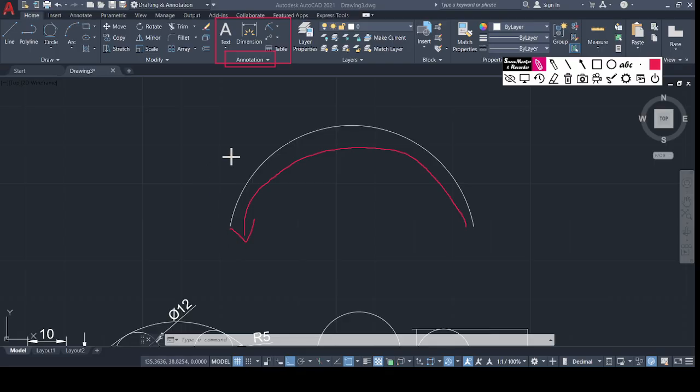So if we have to draw an arc using a start and center, or a start, center, end command, you have to provide the start point over there, always in this direction. You do not need to just click over there, in this direction. Understand? And the end point will always be anti-clockwise. Let's see how it's drawn.